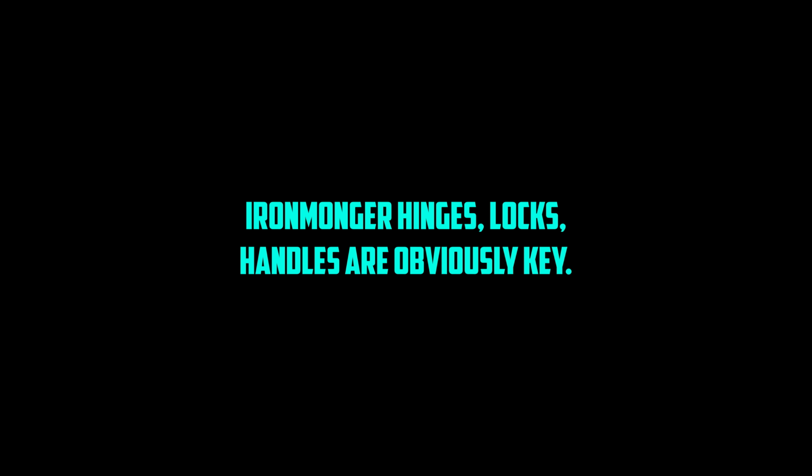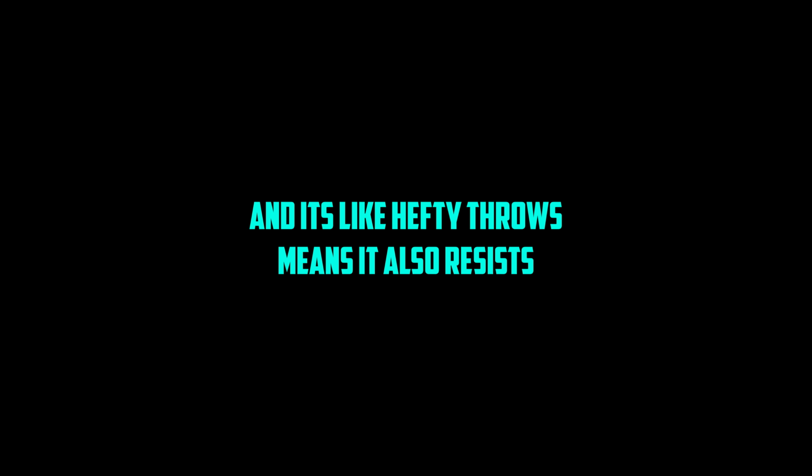And ironmongery, hinges, locks, handles, are obviously key. Fire doors are rated for safety. Yes, usually FD30, 30 minutes resistance, or FD60, 60 minutes. Resistance covers integrity, stopping flames and hot gas passing, and insulation, limiting heat transfer. Standards like BS 476 apply. And FD30S means it also resists smoke spread.